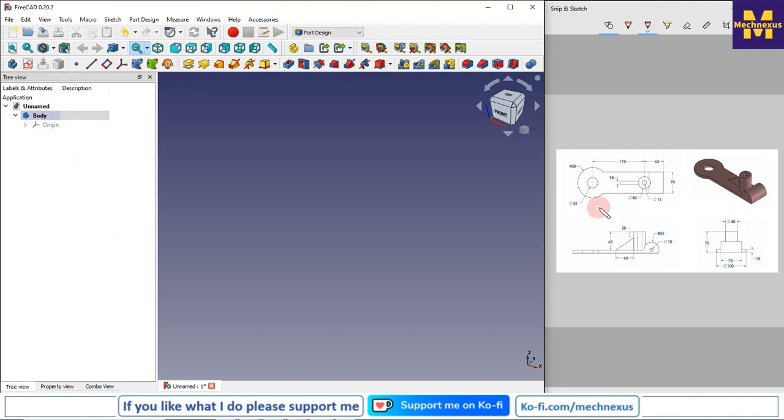So we can see that our base profile is like a plate, and it has one boss and one stiffener plate here. We will start creating our part with this base profile, and then we will extrude and make the cut.